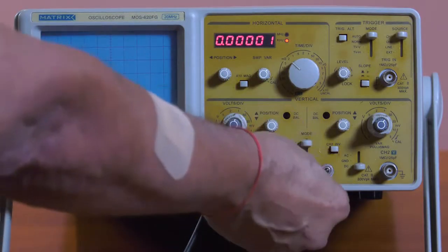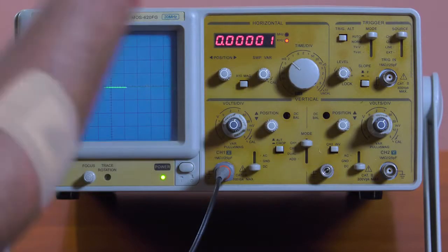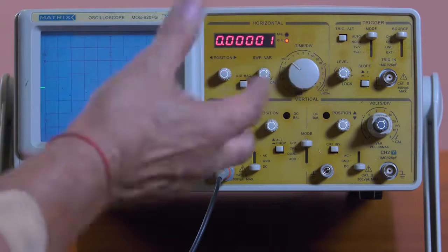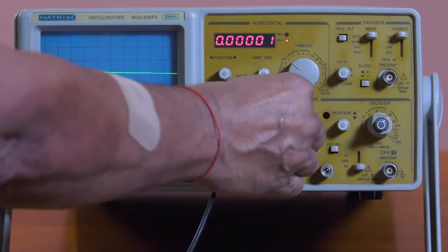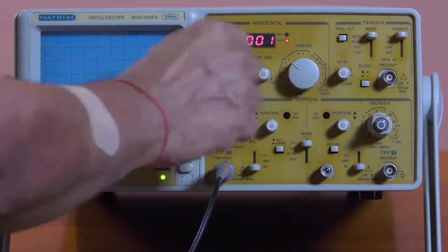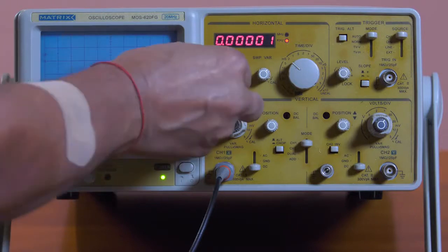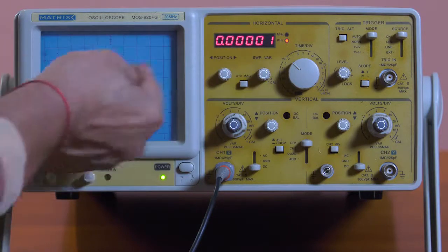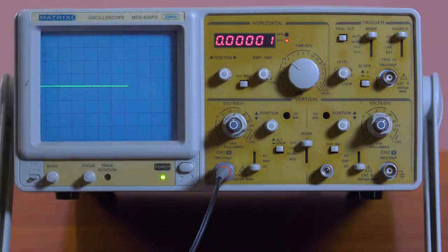You can also have a situation where you can chop, where it shows you one and then it shows you the other at alternate times. You have position buttons which can move the trace, in this case up and down, which is vertical. You also have position button here which can move the trace. As you can see, it's disappeared, your horizontal on this side or that side. That's just to give you a centralized position where it makes life easier to make measurements.